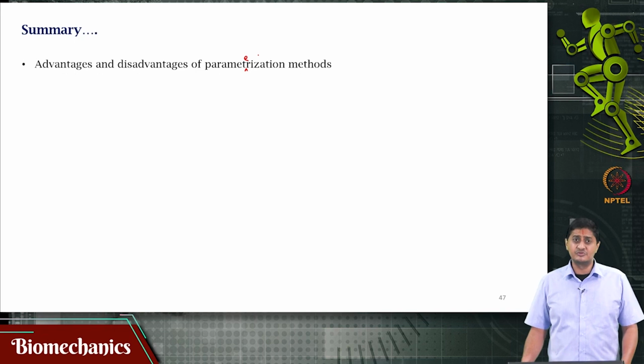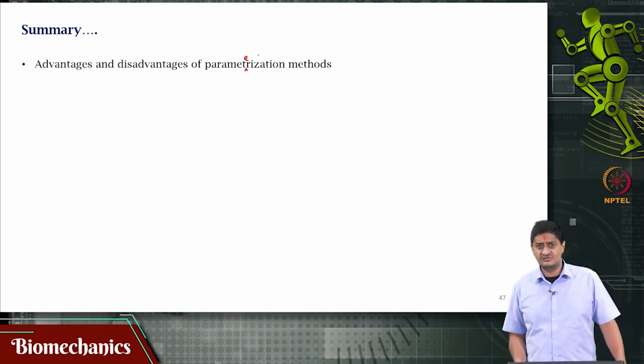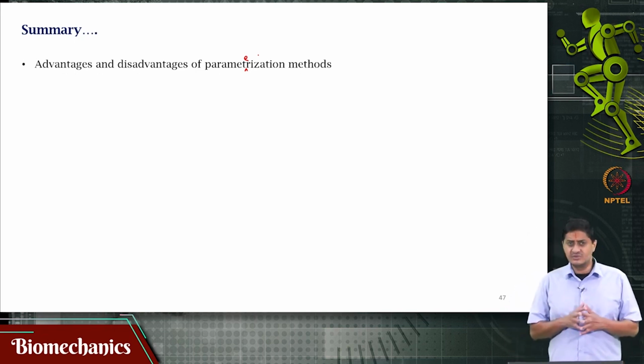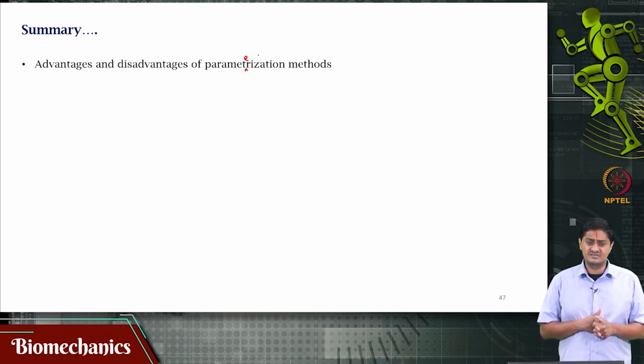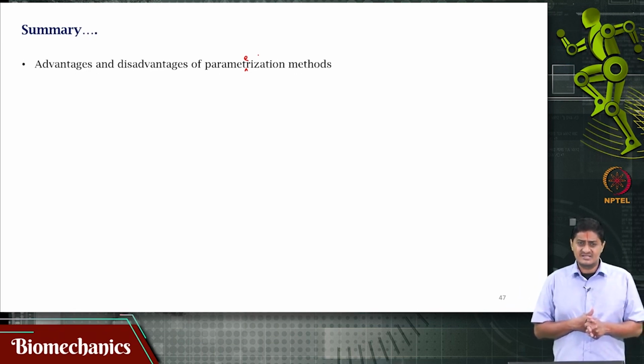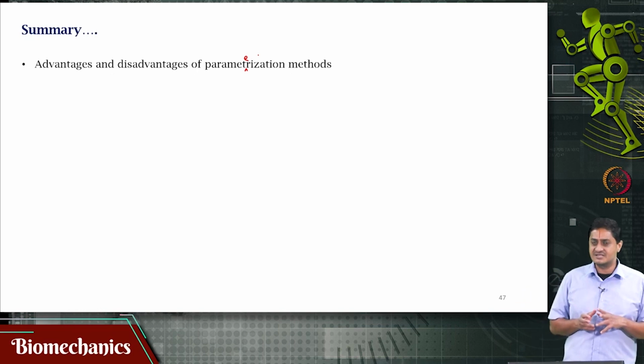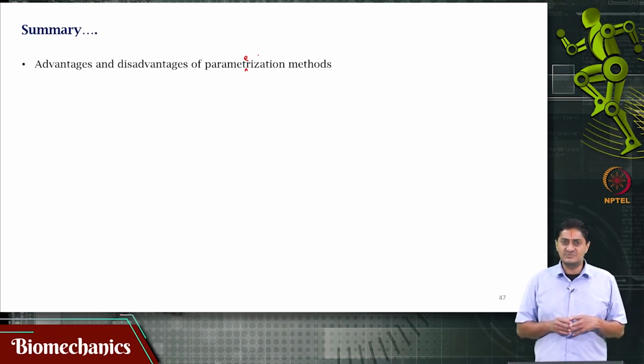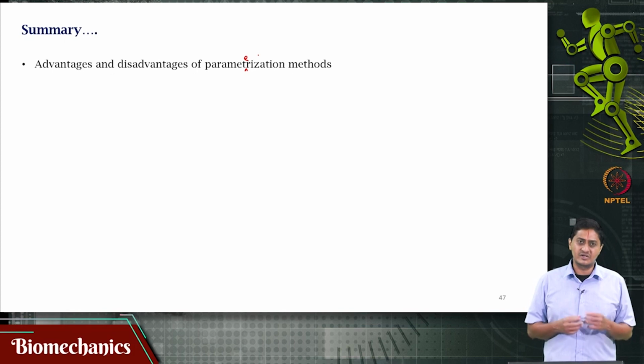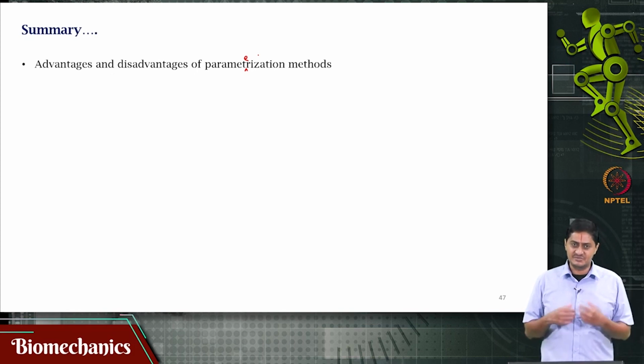To avoid the gimbal lock or singularity situation, you should orient your measurement system such that the middle axis is not required to measure more than say 75 degrees, and the other two axes are not required to measure more than 180 degrees. This is how you align. The choice of axis is dependent on the specific application. So, as the experimenter and the expert in the field, you need to know how to orient your measurement system.